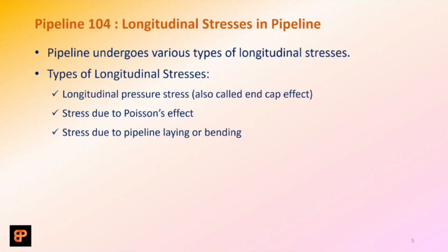But if the curvature or profile of the land or terrain is lower than the elastic radius of the pipe, and you are going to force the pipe to follow that particular radius and backfill it with the soil cover, there will be laying stresses acting in the pipe, which we need to limit when we are calculating the combination of all these longitudinal stresses together, which is also sometimes called the net longitudinal stress.